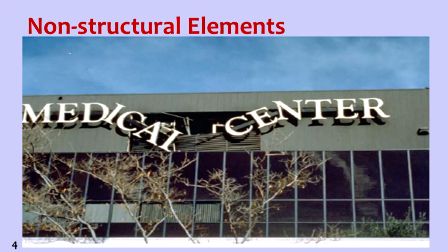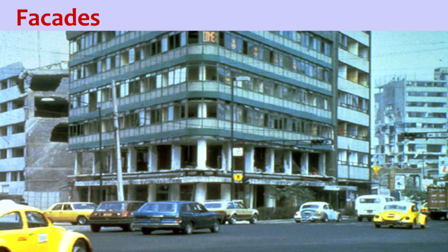So what are non-structural elements? You can see this one, say glass facade. That is a non-structural element, as you can see in this slide. And then you can see heavy facades. These days, especially in urban areas, glass panels as big as 3 meter by 3 meter are installed at the top, maybe 30 meters or 40 meters height. So we need to understand the dynamics of these non-structural elements.